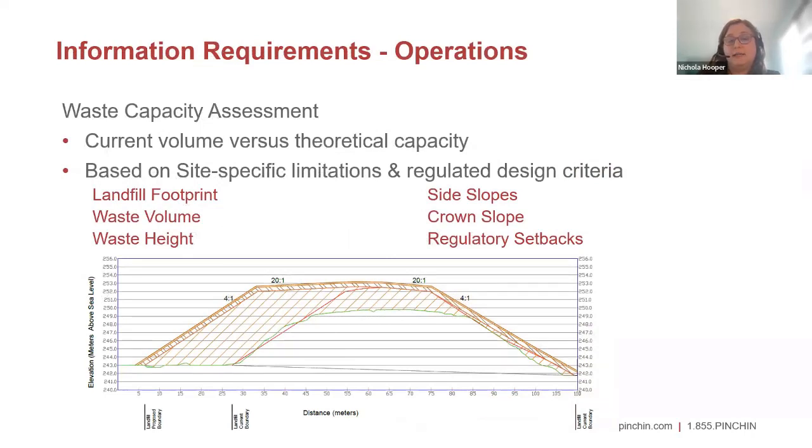For closure costs and post-closure liability, you need to know where your landfill is at today. All landfills have limitations on them, whether it is the amount of waste that you're allowed to receive by volume, or it could also be based on the areal extent. For example, you could have a limitation that your landfill can only be 2 hectares large. There are also height restrictions, side slope restrictions, crown restrictions, and regulatory setbacks. Most of the time, these will be specified in the licenses for your landfill.